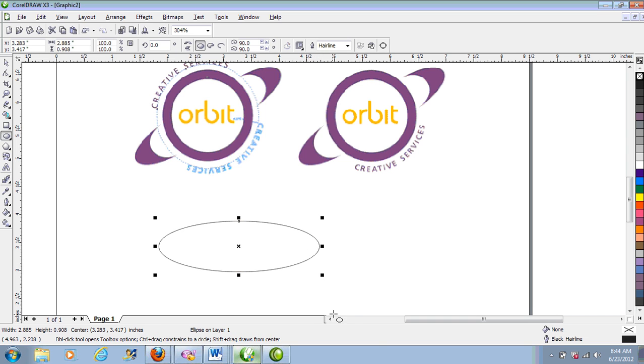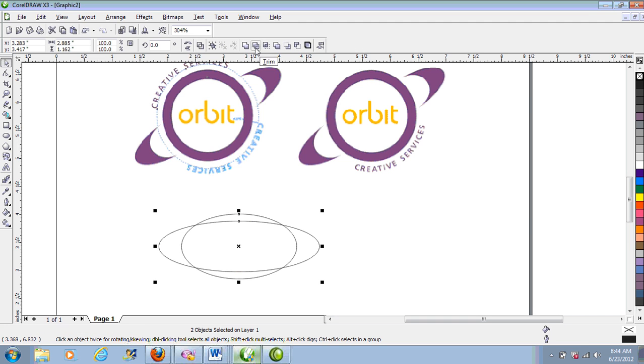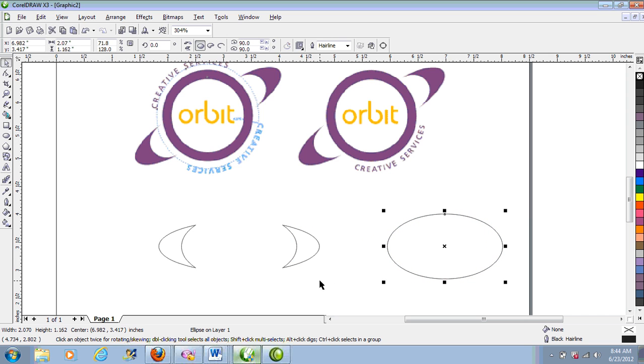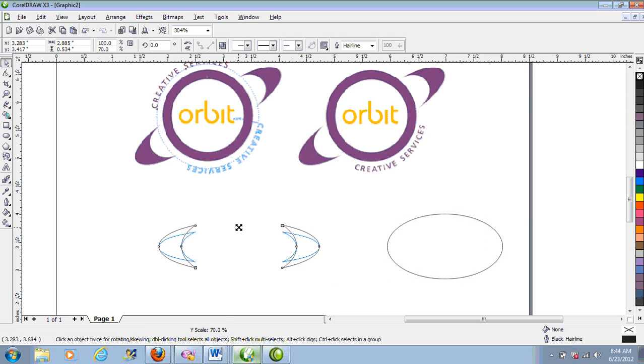So this is the ellipse tool. I drag it to a point that I know is going to be okay for me. And the next thing, I need to duplicate it so that I can achieve what I want. Just watch and see what I'm trying to do here. I'll use this second, inner ellipse to cut the outer one. So I go to trim and cut it out. The middle ellipse, I don't need it. This is what I need. In order to achieve what I want, I need to shrink it, clicking and dragging one of these nodes.